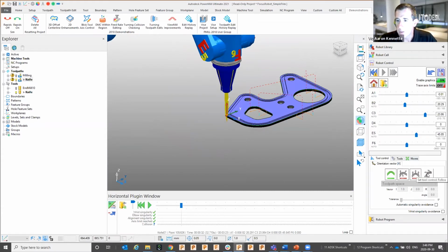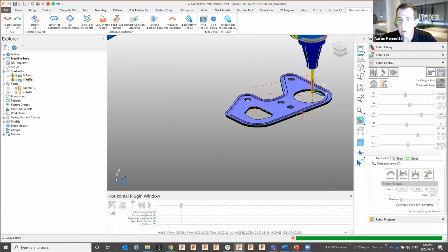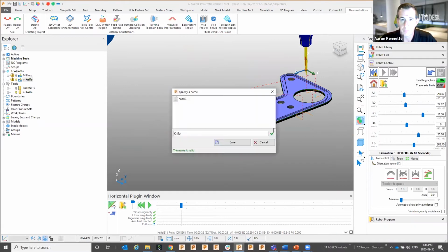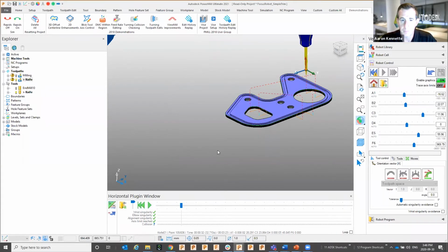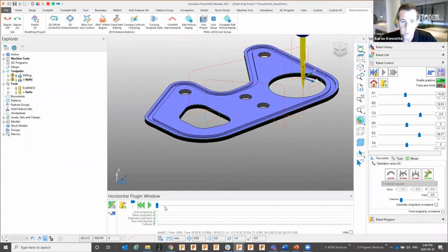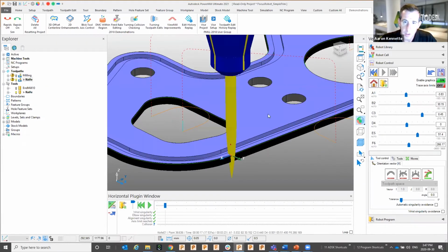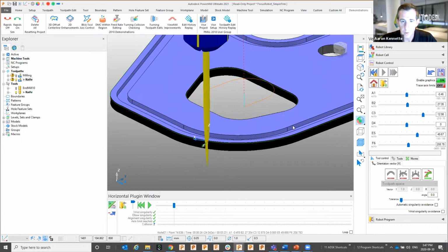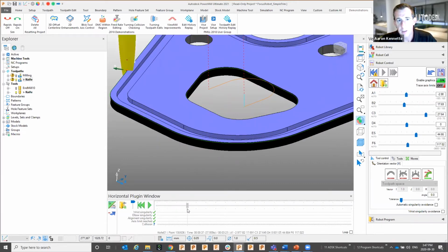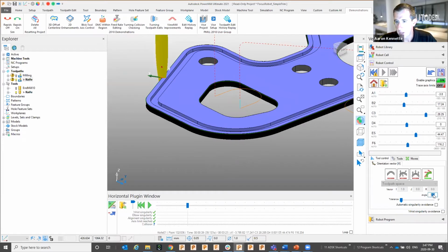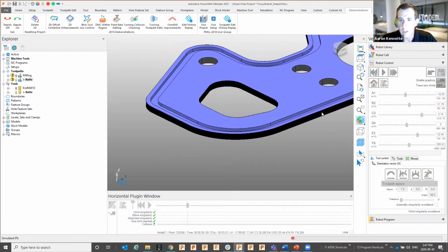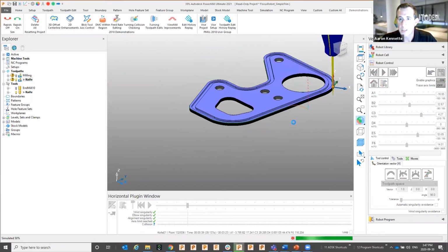So what we can do is set the option to an orientation vector of follow. We can restart and resimulate that toolpath. Now if we zoom in, we'll see that we're following along the edge as we're supposed to properly, except again, we're 90 degrees out to what we want to be. To fix that, it's just a simple angle change. You can enter in a 90-degree value here. And now you'll see that it transitions through that area as it's supposed to, following the cut.